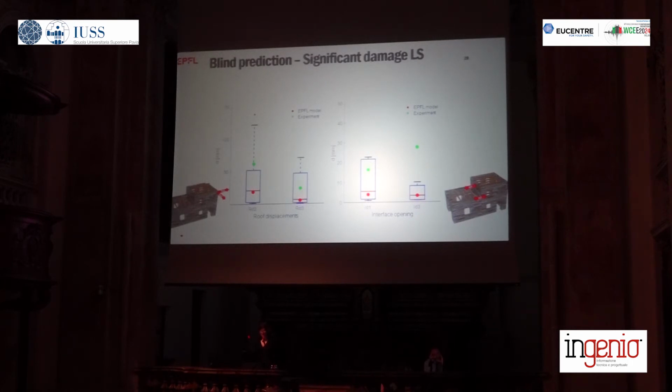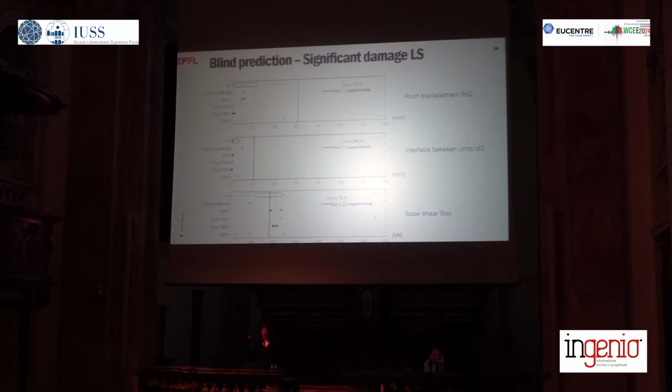So these are really still ongoing investigations, so not everything is settled yet, but here are just some first results. One thing that was really striking is that the displacement demand estimates that came from discrete element models, abbreviated here as DEM, were much better than from finite element models, so equivalent frame models, shell models, or solid finite element models.